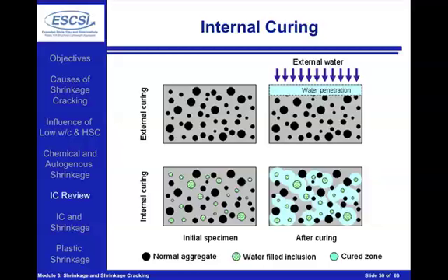Now, in a high water to cement ratio concrete, this water penetration depth can be quite large. However, as we reduce the water to cement ratio of our concrete, as we use materials with a more finely ground cement, smaller particles, nanoparticles, silica fume, what we're going to notice is we're going to densify that concrete. That's one of the main reasons why we're using those materials. The more dense we make that concrete, the harder it's going to be for that external water to penetrate and fill in those vapor-filled spaces that are forming in the center of the concrete.